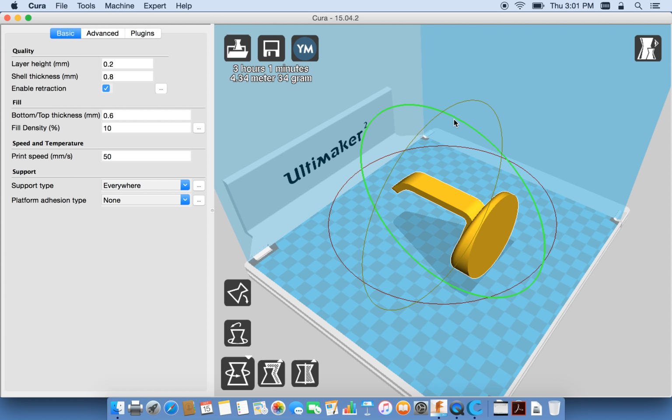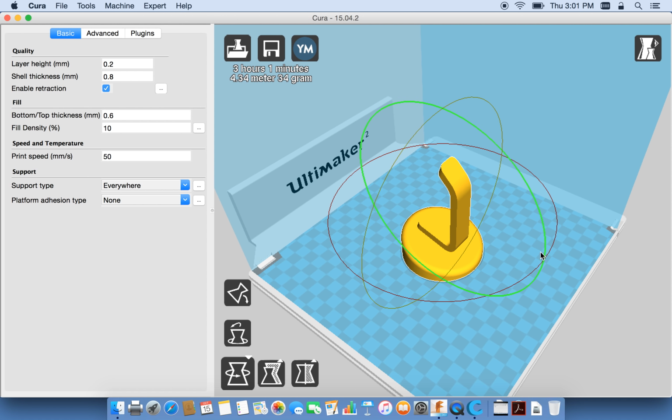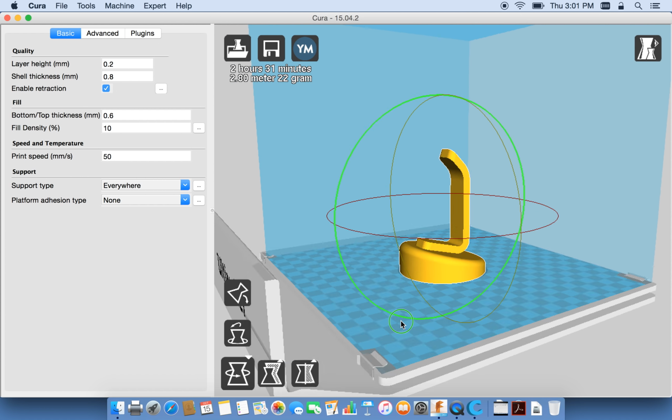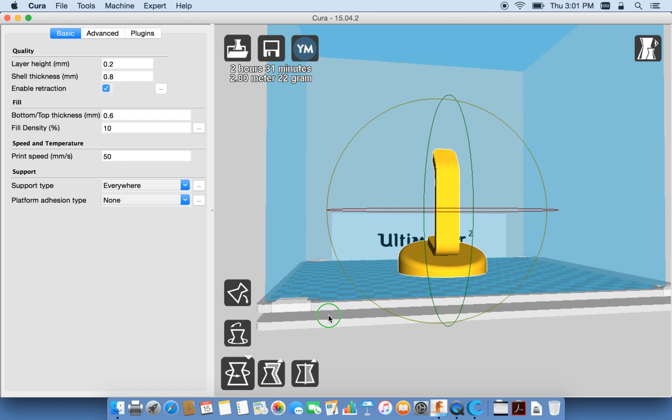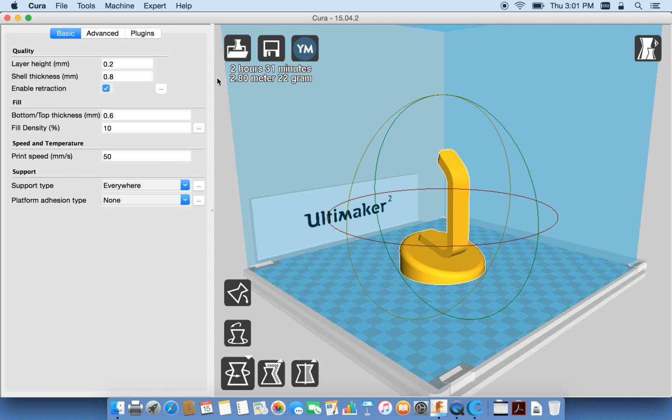I still do need to rotate it because of the way it was built, the orientation. I could probably tell it to change that. I do, is it a 90-degree turn? And now remember in Cura, it's a right click to turn and spin and do your rotation. So that one at 20% is still going to give you about 2 hours.